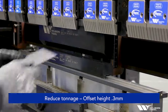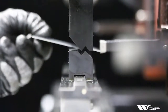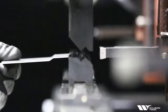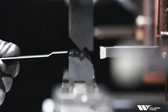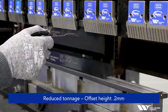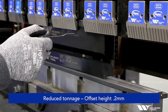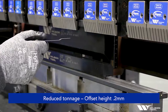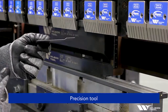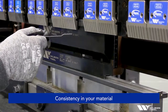And the fourth bend, we'll back it off even a little bit more. Let's just back it off enough so that we have a very lazy offset. It's very lazy, but I'm still controlling the height. So if I wanted my offset to be this height, I could control the stroke and I would get great repeatability out of it. As long as you have the three common things that you need to air bend, which would include a precision tool, repeatability in your stroke, and consistency in your material.